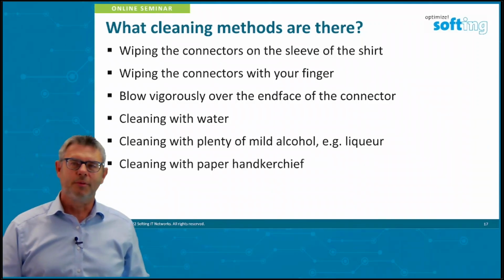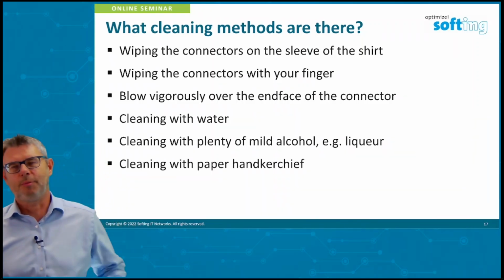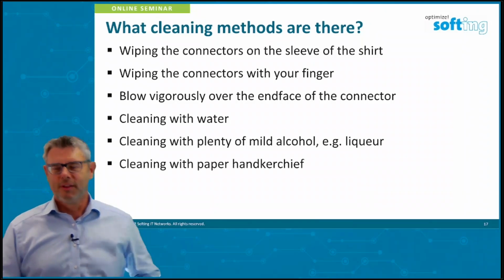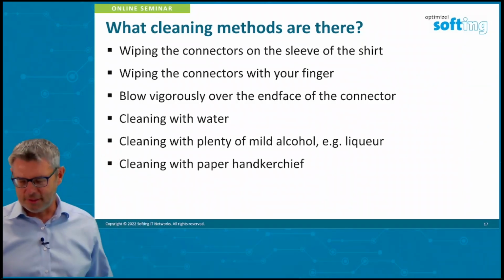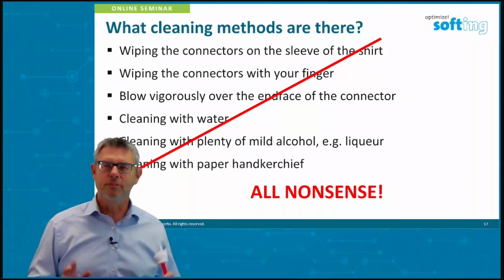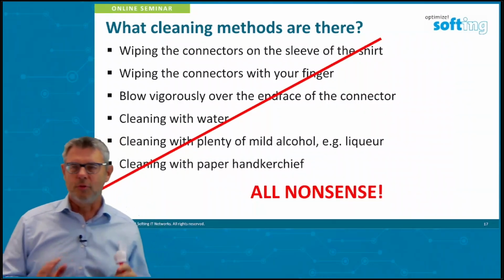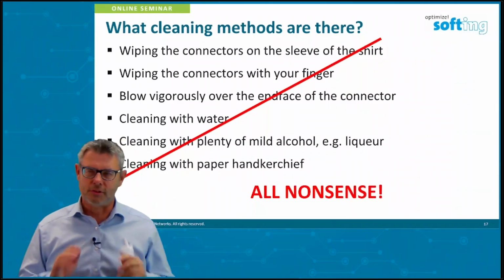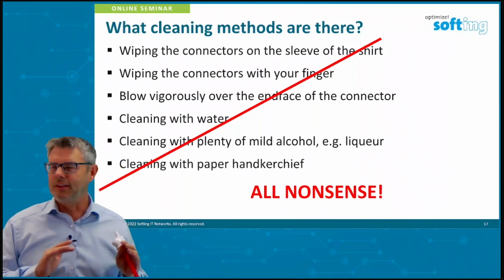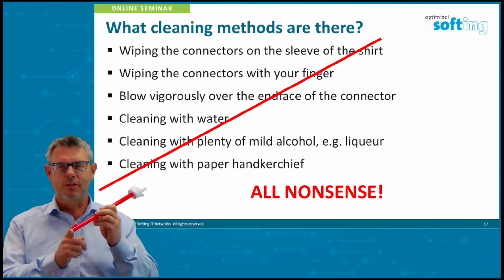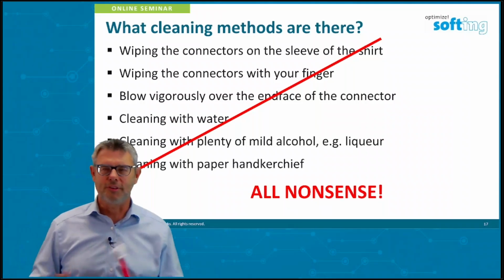Or very common, cleaning with paper handkerchiefs. Okay, of course, all these methods I learned are complete nonsense. Don't do it. You get more dirt on the connector. You are destroying the connector. Cleaning with water, the connector is soaking in the water. Don't do this. Okay.